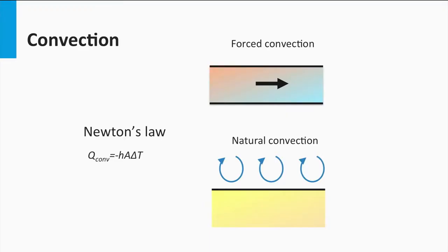In both cases, the heat transfer can be described by Newton's law, in which h is the heat transfer coefficient in watts per square meter per Kelvin. I won't go into detail on how to calculate the heat transfer coefficient, but it's important to know that it will depend on several operational factors, such as the velocity of the fluid, the shape of the surface, or the kind of flow that is present.